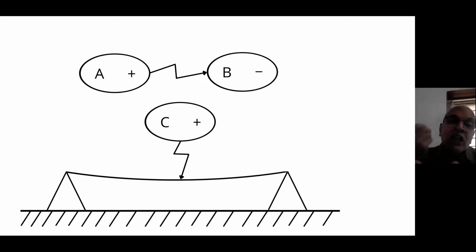It is bound. But now it so happens some third cloud A comes nearer to B and there is a stroke between A and B, internal or in the air. Positive and negative get neutralized. So the positive charge on C becomes abruptly free. So the negative charge that was induced on the transmission line becomes abruptly free.